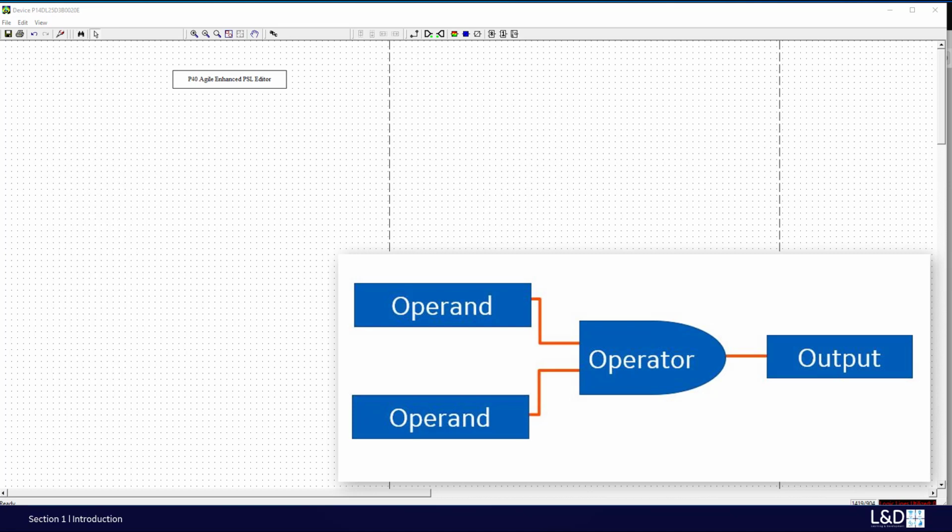The output of the operator typically is the virtual output, but can also be the programmable LEDs or the output relays. And in the end, these LEDs and output relays are still using the virtual outputs. The relay output contacts and the programmable LEDs have dedicated conditioners to create the delay for pickup, dropout, or pulse output, etc.